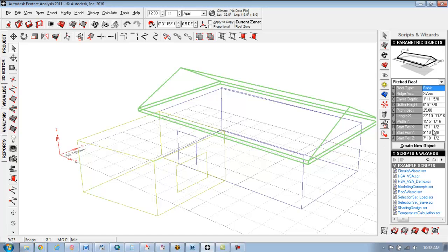Okay. So over on the right-hand side here, we'll get into these in a second. On these different tabs, you can specify some more specific, detailed information. There's no properties navigation toolbars or anything like that that'll pop up. So it's all done from this right-hand tab side. So if you needed to adjust the depths of your eaves or gutter or the height, you can do all that here. You don't have to necessarily just do a standard pitched roof. That's the default. But to pretty much do all non-orthogonal shapes, you can do that from this Parametric Objects tab, which is this one down here.